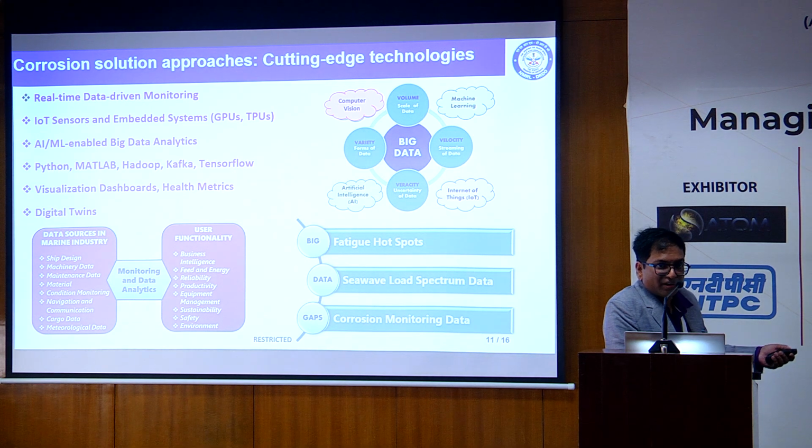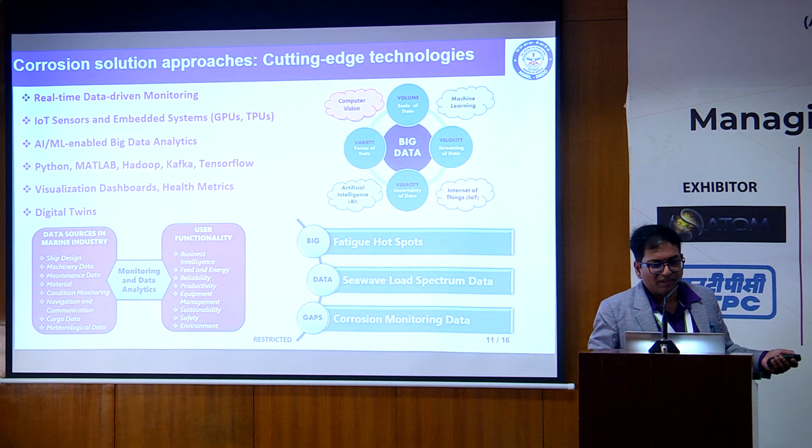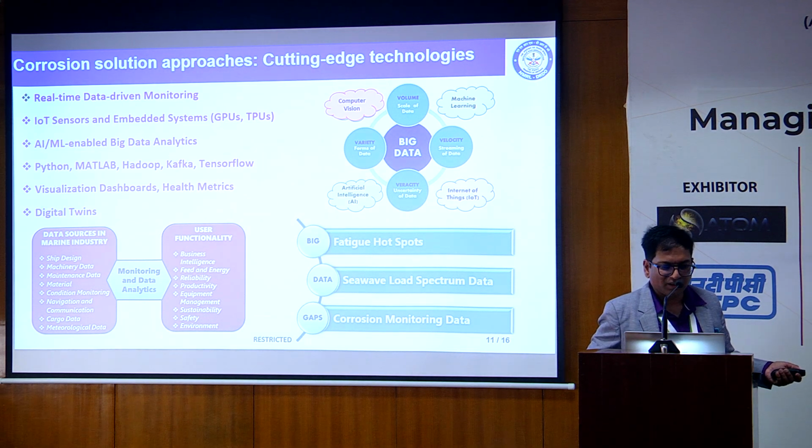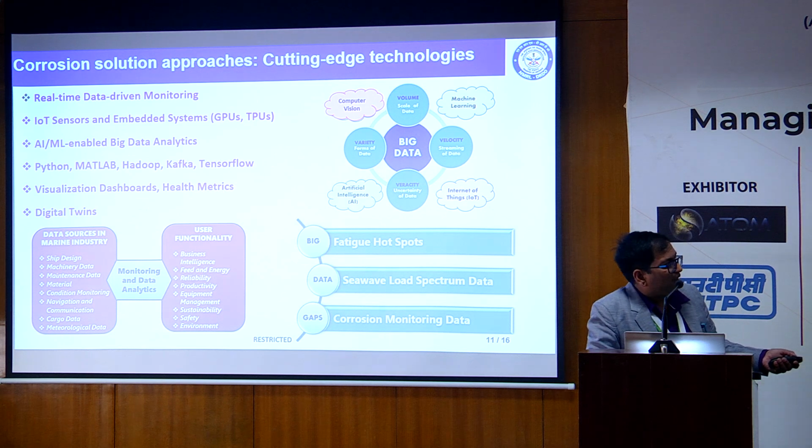structural health twin monitoring? The previous speaker explained using combined FEM, or rather extrapolated the application of FEM, with sensing technologies and dashboards and all those things. With respect to ship hull corrosion fatigue monitoring, it is basically a corrosion fatigue phenomenon, because the sea waves are actually 0.1 hertz, and as the previous speaker and sir mentioned, low frequency is more detrimental in terms of corrosion. So these are the big data gaps.